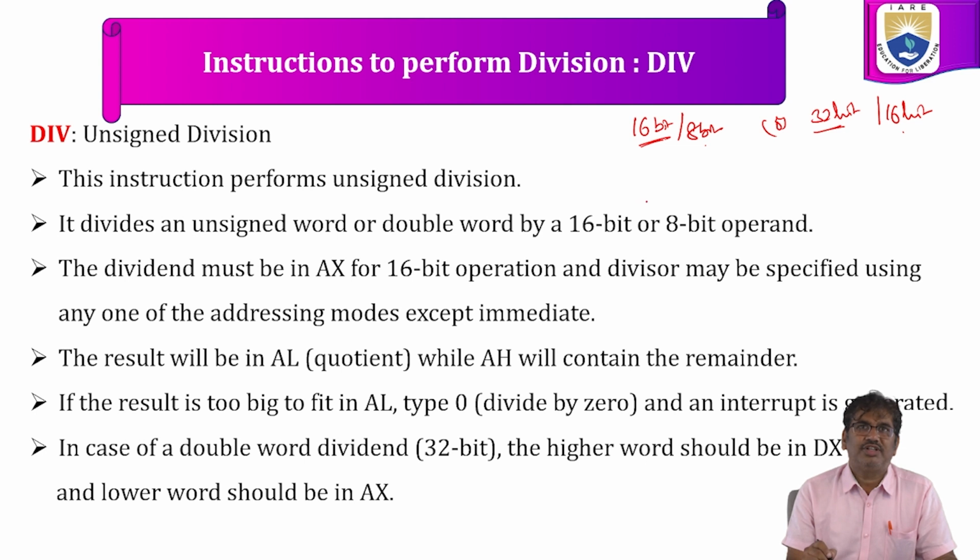The dividend must be in the AX register if it is the 16-bit case, and the divisor, which is 8-bit, we can represent in any one of the addressing modes, like register or memory.